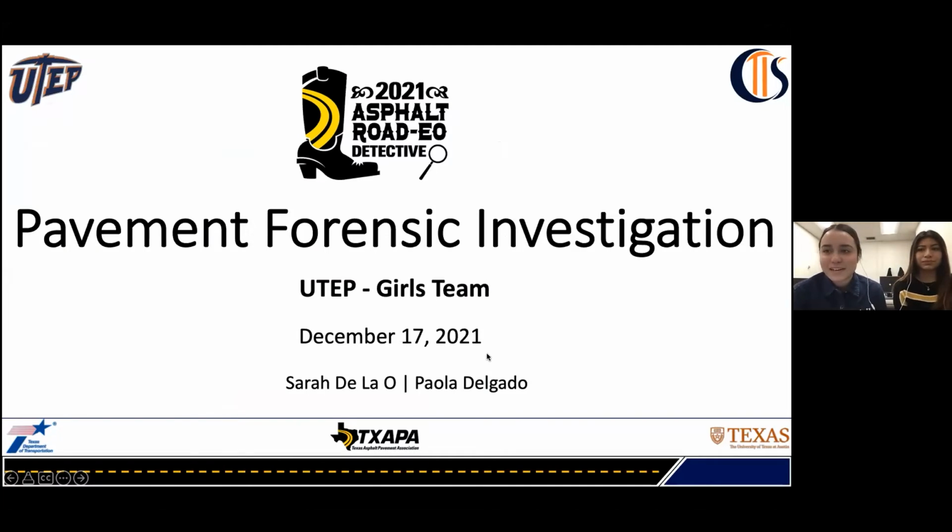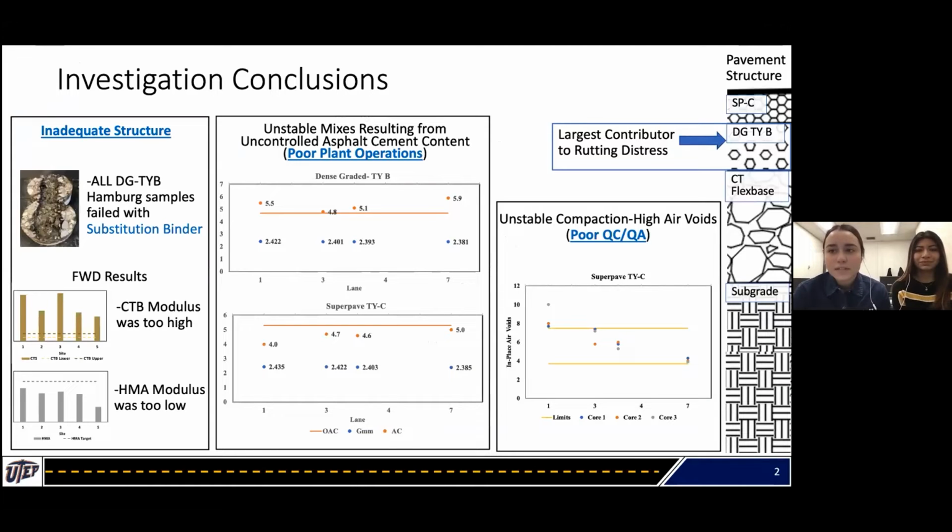Good morning. My name is Sarah De La O, and I'll be presenting our conclusions on behalf of the girls team from UTEP. First, we determined that the rutting was due to an inadequate pavement structure. This was concluded because all Hamburg specimens failed to meet the 15,000 cycles required for a PG of 70-22 when it was substituted with a PG of 64-22. Additionally, the modulus of the cement-treated flex base surpassed the target range, indicating that the pavement was too stiff, preventing it from becoming flexible. Second, there were unstable mixes resulting from uncontrolled asphalt cement content or poor plant operations, as the specific gravity of the mixes varied a lot throughout the different lanes.